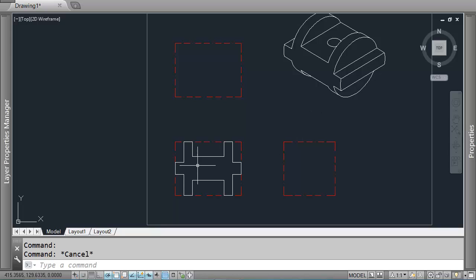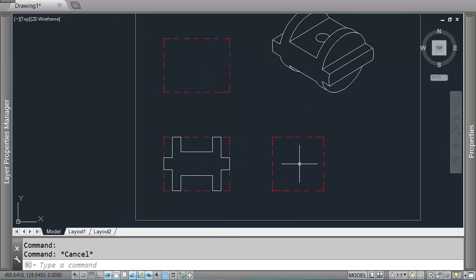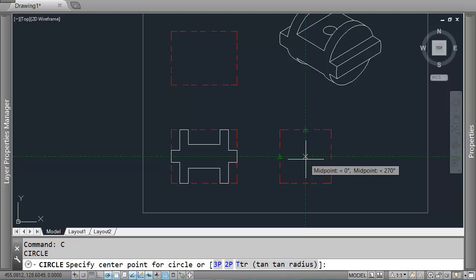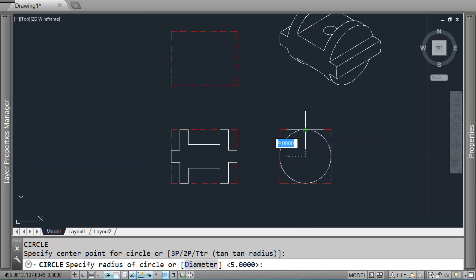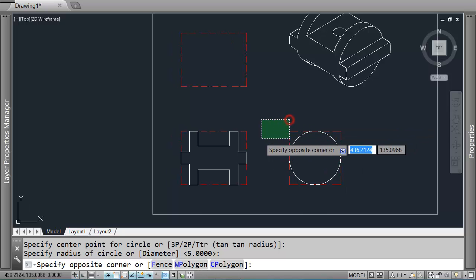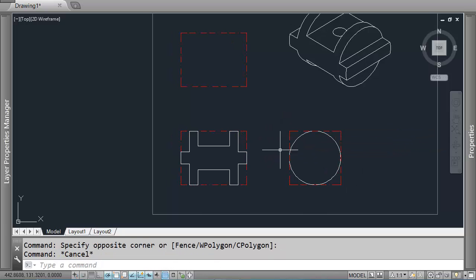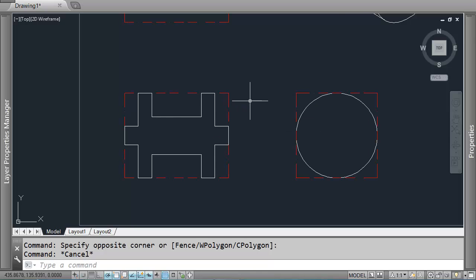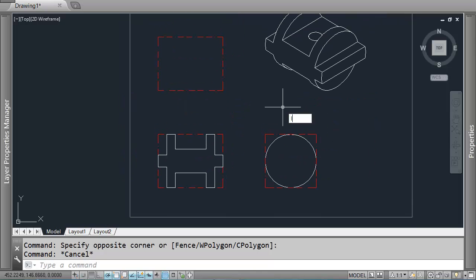The next view that I'm going to draw is this view off to the right, because there's information needed to draw the top view, which we can obtain from the right view. So we'll start with a circle which is centered in the middle of this draw box, and it just touches the outside edge. That's how these draw boxes are always set up, by the way, in this little script. They're always set up to be just the outer extents of the shape. So if your shape ever doesn't touch the outside edges, you've probably measured a line wrong somewhere.